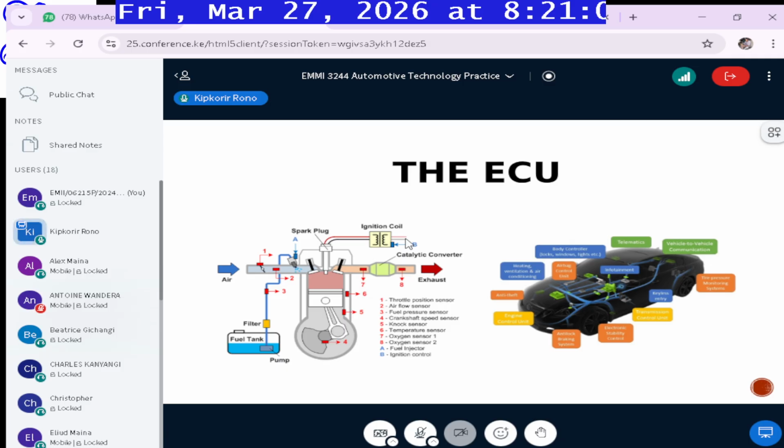For example, if you are having incomplete combustion in some of the cylinders, especially if you have very worn out spark plugs, then you are having intermittent power production, which means sometimes you are skipping some power strokes. If you skip some of these power strokes, you will have very inconsistent production of power. Sometimes it shows as vibrations in the engine, so in some cycles you have some extreme vibrations.